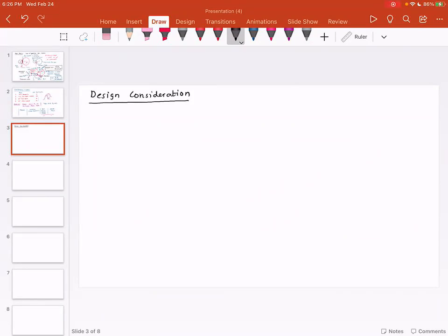So at that time, we have to choose the appropriate material, we have to choose the appropriate heat treatment, we have to choose the service factors, and we have to look at the operating conditions. We have to make some assumptions and then start with a basic skeletal design and make sure that that design is safe in all possible operating conditions. If that design fails at certain point, we have to go back and revise the design.